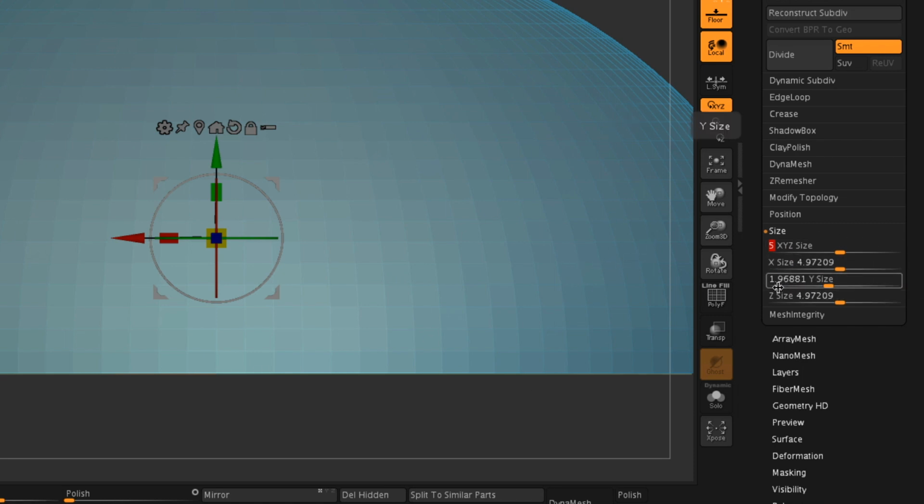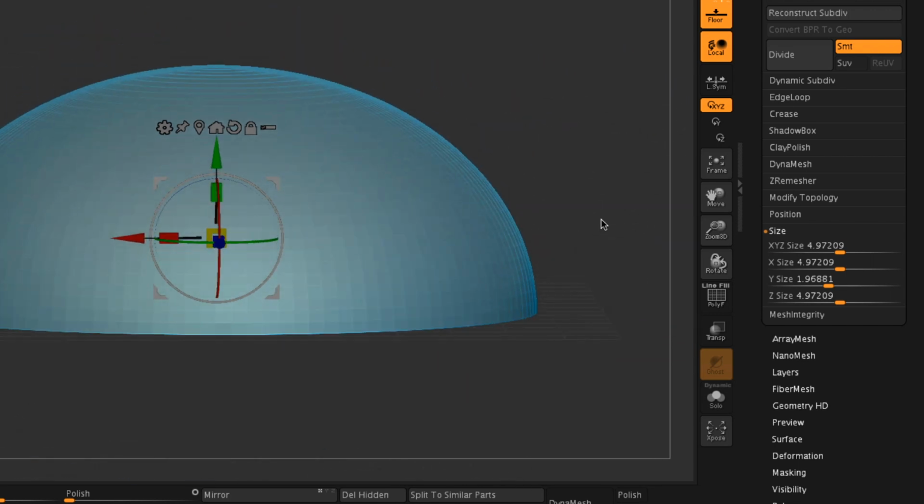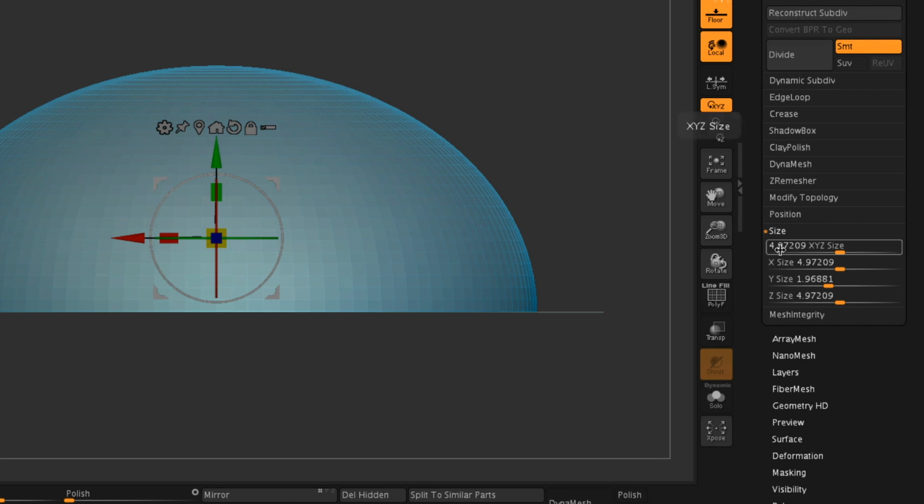The Y size is this top to bottom size. And if you're using a particular stone, you could adjust these. So if it's actually 5.1, or maybe 2.2 millimeters high, you can switch these numbers to make it accurately reflect your stone. So what do these numbers mean? These numbers, when I'm working in ZBrush, are the millimeters of size that I'm working with. So as of now, this stone has been resized to approximate a 5 millimeter stone.